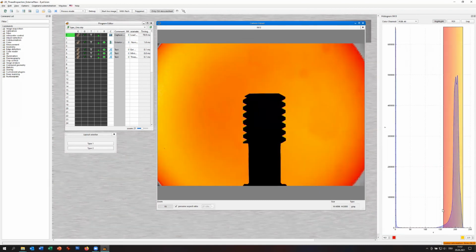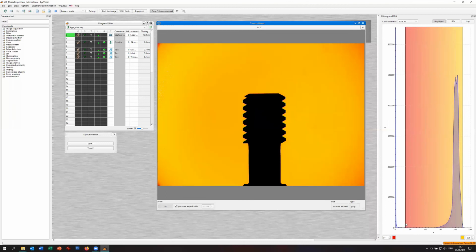I didn't tell this, so the contrast is at least between, let's say, 10 and 150, which allows to have real stable values. You should always try to have between the part and the background a big gap, so that the algorithms have an option to decide when they find an edge or not.